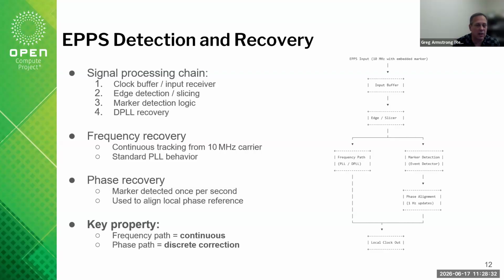And there's other ways you can use that marker, right? That we can output it. There's been talks about using the TGPIO, where you can output a digital signal that represents that 1 PPS. You can use it to go out to a connector for measurement. That's how the telecom industry uses it as a measurement marker, so everyone can understand where your relative error is in relationship to the absolute UTC 1 second. I can make a measurement off that looking at the 1 PPS.